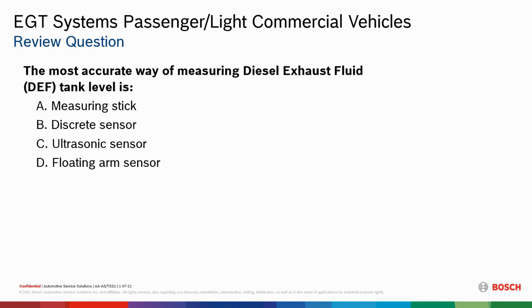The discrete sensor really isn't the most accurate way because we have only 3 sensors in there that measure that probe, and the rest of it's based off of mileage of the vehicle in between those sensors and says, well, I burned so much from 100% to 80%. I should be at that 80% level soon or in between the 80 and the 30% or whatever it is.